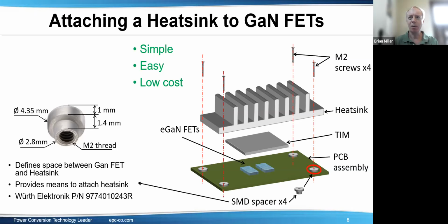I think it depends on what's on the bottom side of the board, if it's connected or whatever. If there's no, it's probably very similar to the GaN. It might be very close to the GaN, if there's no heat flux through it. I'm not sure if the questioner is trying to ask, okay, if you have a heatsink assembly, you put a thermal probe on the bottom, is that close enough? Does it get close enough to the junction of the GaN FET to do an accurate measurement? It could be, but it's kind of a little bit dangerous to do that and assume that's a good way of measuring. It really depends on the board and that particular board and how much gets radiated from the board.